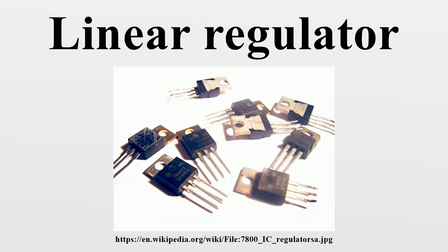Linear regulators are often inefficient. Since the transistor is acting like a resistor, it will waste electrical energy by converting it to heat. In fact, the power loss due to heating in the transistor is the current multiplied by the voltage difference between input and output voltage. The same function can often be performed much more efficiently by a switched-mode power supply, but